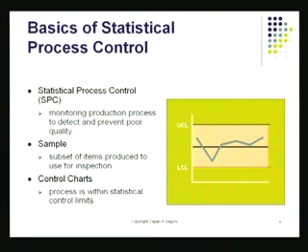I check out the quality of each of them and I compute this quantity called X bar from the sample data that I have. And X bar is what I bring down to my chart, and I plot my X bar, and by plotting that X bar, I basically reach a decision whether I need to adjust the process or can I leave it alone. This device is called the control chart, and the goal of this chart is to try to help us keep the process within control limits or within its natural variation.